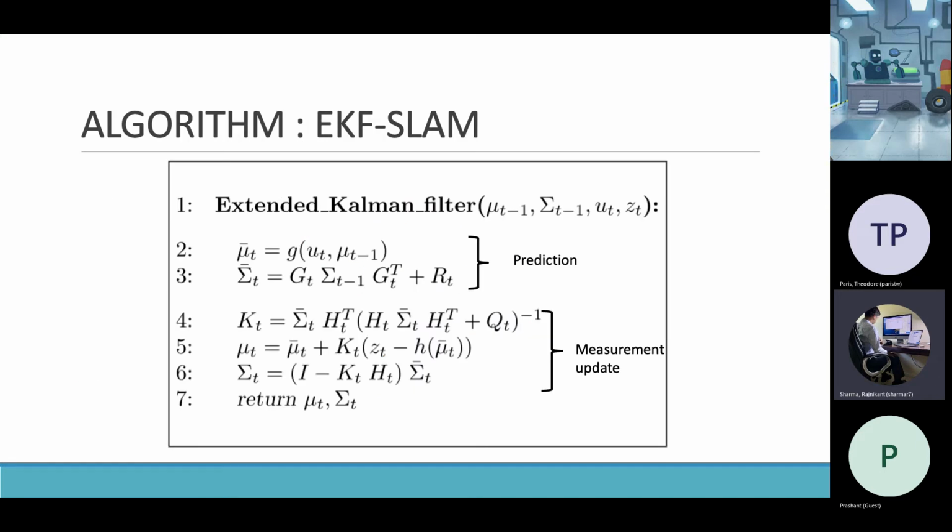So as we know, the EKF has basically 2 steps, the prediction and the measurement update. So we just use the same motion model, the V sin psi, V cos psi, and omega to propagate our motion model. And then we take the 3 range sensor data to update our states and the covariance. So the only difference here is our states would kind of remain the same, but the covariance matrix would keep changing with the measurement update.